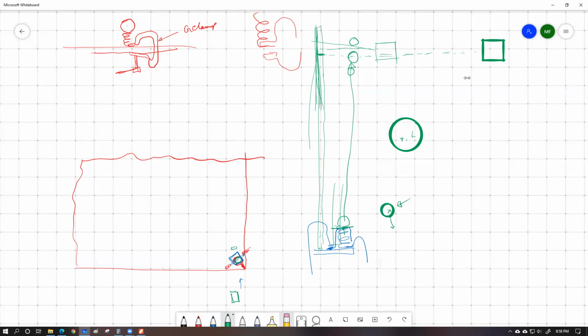You don't know exactly at which level it's going to get a perfect jump, because some amount of energy is definitely wasted because of the friction, and some amount of energy is wasted because of the non-uniformity of the spring's compression every single time. Because whenever you are placing the tape over the diameter of the spring, somewhere over here, this is the top view, you cannot always ensure that you are placing it on the exact diameter line. That's what you're going to try to do, but being able to do that every single time without fail with appropriate perfection is not possible. So you're not going to have it at every single height.